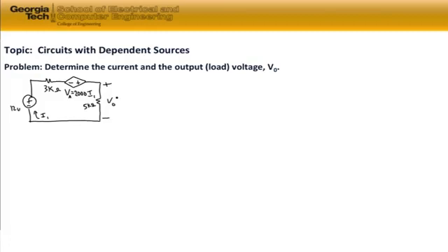So in order to do this, we want to use Kirchhoff's voltage law, and we can do that by summing up the voltages as we go around the circuit, and we could choose either a clockwise or a counterclockwise direction to add these voltages up, the voltage drop associated with each element. It really doesn't matter whether we go clockwise or counterclockwise. So we're going to, in this case, start with the lower left-hand corner of the circuit, and we're going to go clockwise around the circuit.